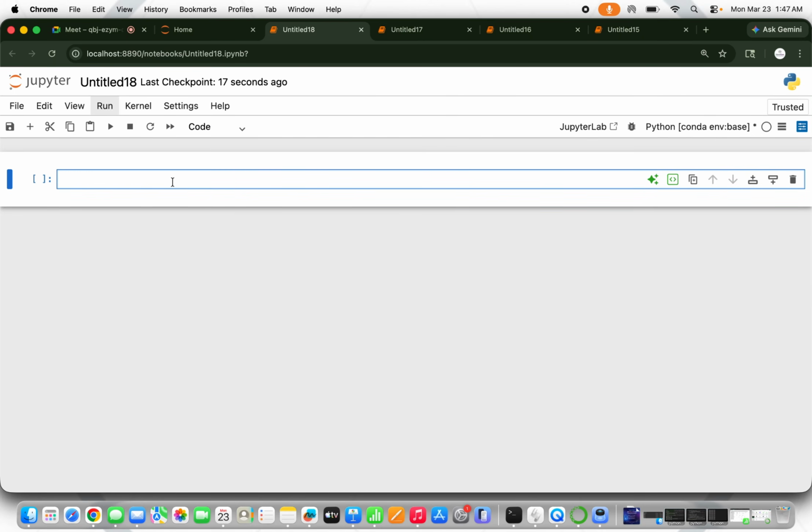Let's write the formula first. I will mark down this line to write the formula, whatever we have seen. So your throughput will be equal to your NRB, the number of resource blocks, into 12 subcarriers, into your modulation, whatever modulation you are using.